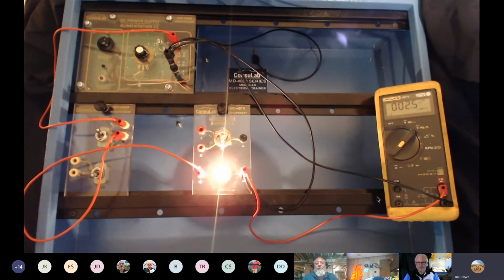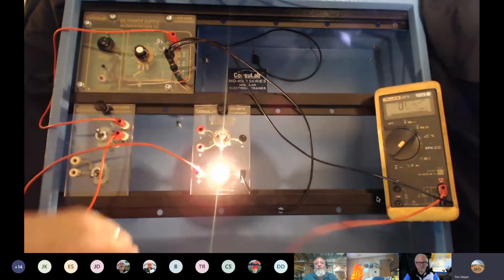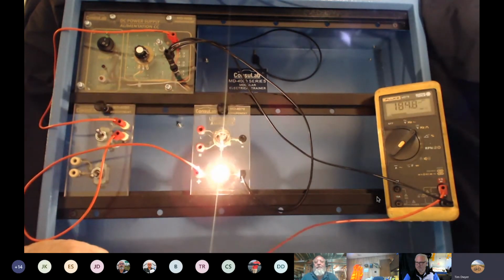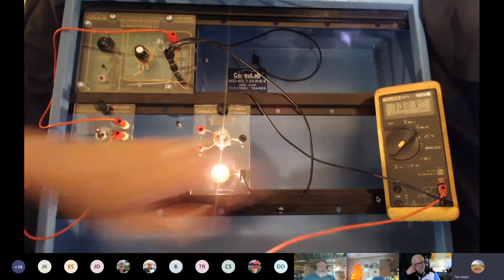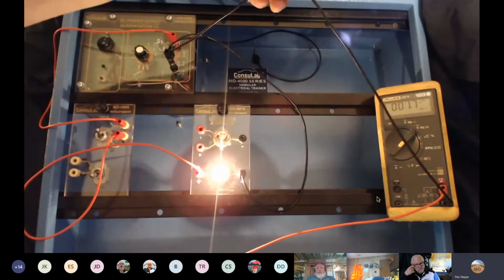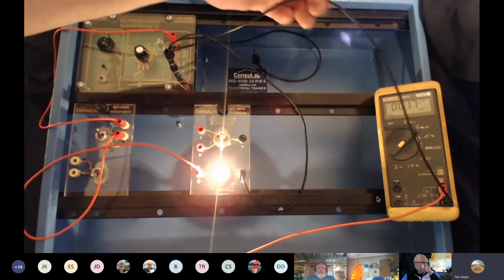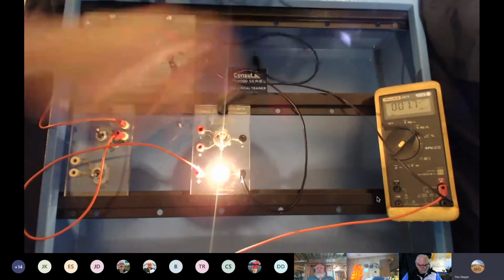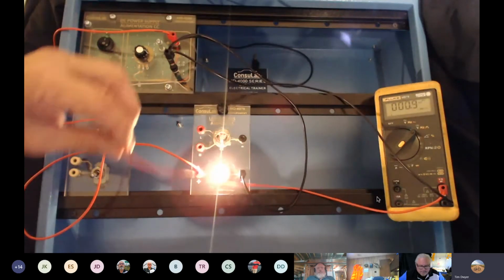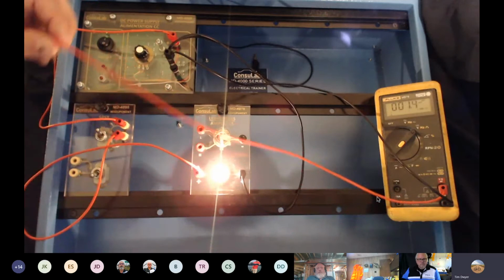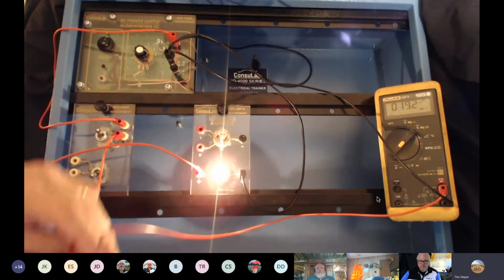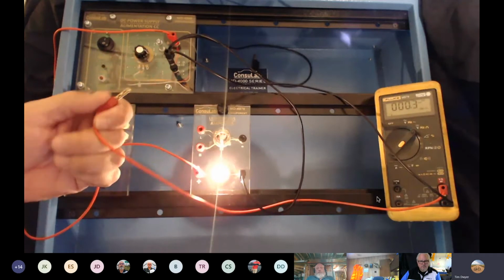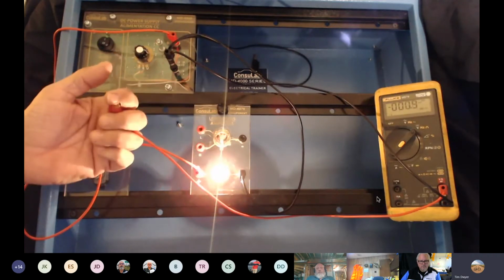So real quick, let's talk on a functioning circuit here just for fun. I want to do a real quick voltage drop test, and I know you were real big on ground reference voltage drops. So technically that means leaving my DVOM stabbed at the battery post is what I always say. It's grounded, and then I'm going to go around with my meter and compare. Really, what you need to tell your students, all they're doing when they make a voltage measurement is comparing the difference between the two leads. Okay.